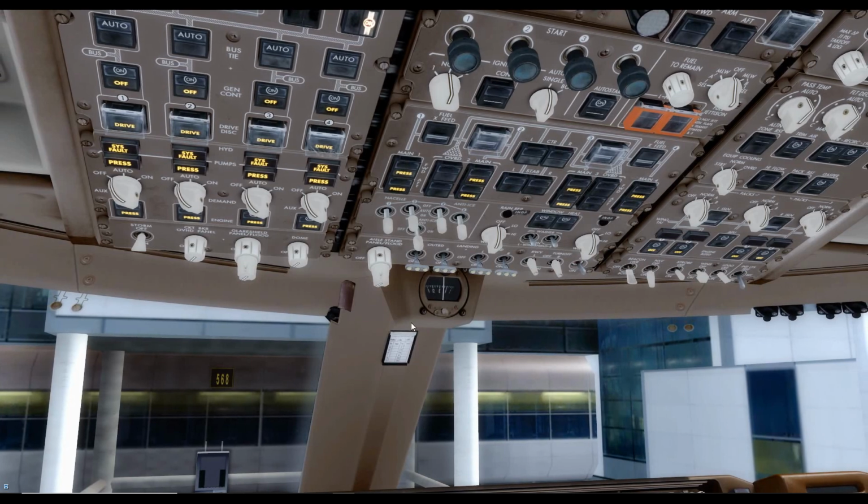As for the lighting panel on the leading edge of the overhead, you can set the internal lights to your heart's desire. If you're operating at night, then you'll want to make some selections on here. As for the external lights, the only ones we really need to have on during the day are the nav lights at this stage. Everything else needs to be off, including the landing lights, the turn-off lights, the taxi light, the beacon, and the strobes.